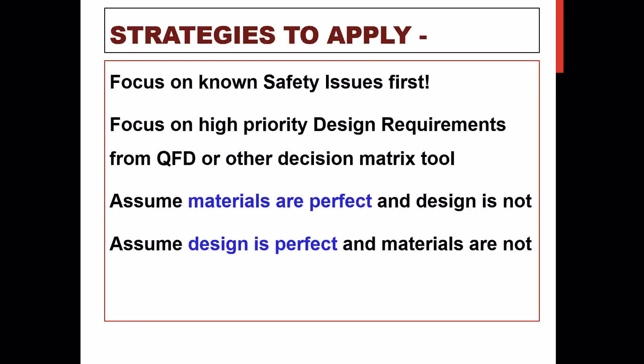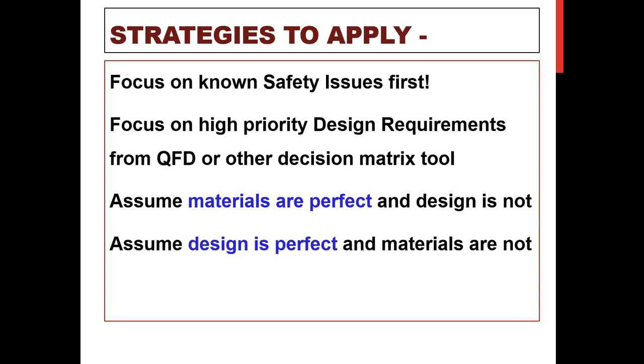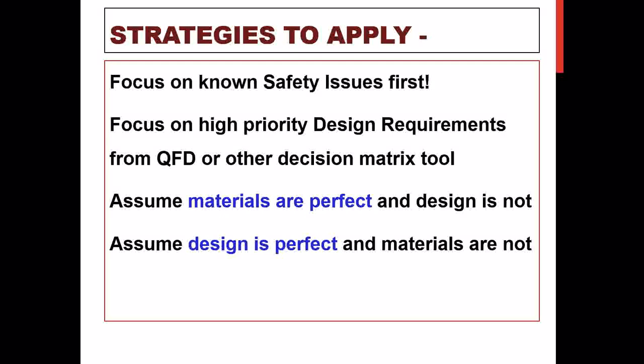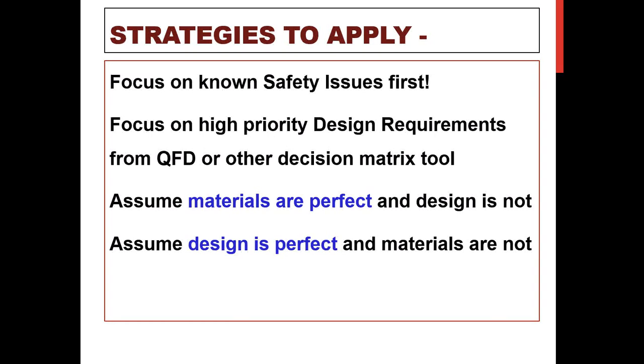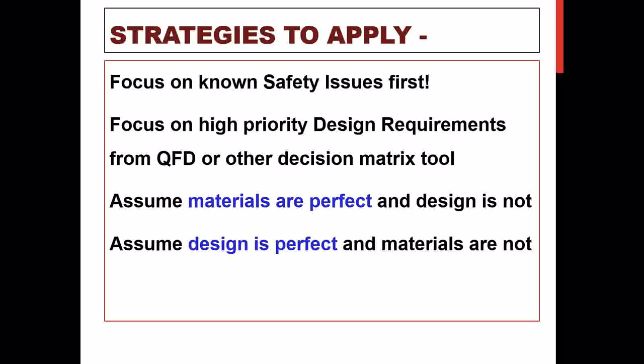So we put this all together. The next step we're going to do with our design FMEA is determine the actions that we're going to take to reduce these RPNs. So in the case of some of these high rankings here, we pulled them together. We're going to say that for the input system, we're going to run a full analysis. We're going to look at stress, friction, and wear, and we're going to address those issues for the bearings and the shafts. We're going to set somebody to track that. In this case, we've got an engineer by the name of Mr. Heisey who's going to go in and track that.